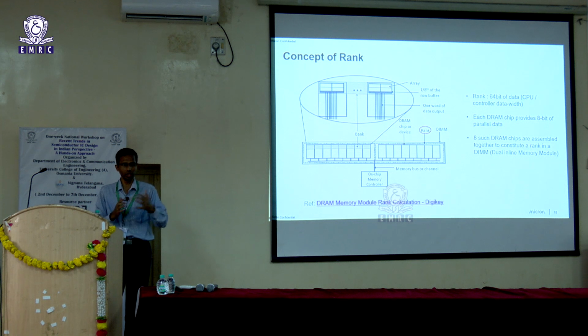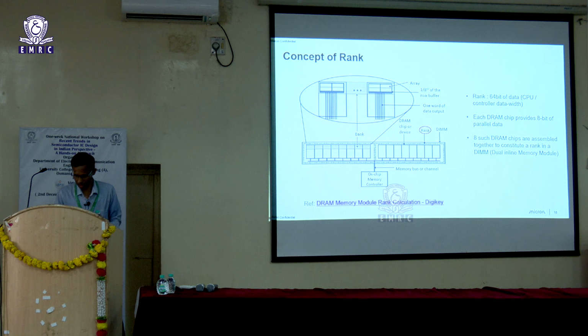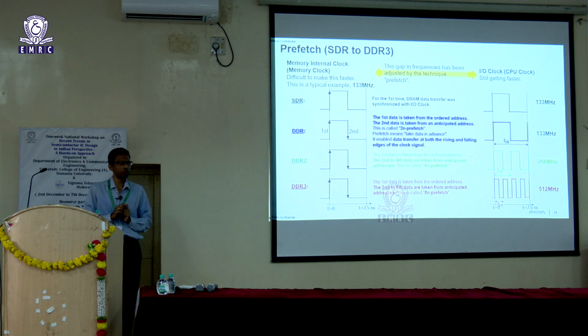So that way you are now growing your memory size, but still retaining the same bus width. So that's the rank, which is a very useful feature for increasing the capacity of your system. The other concept is called a prefetch.